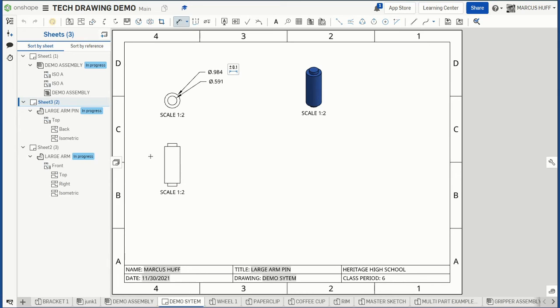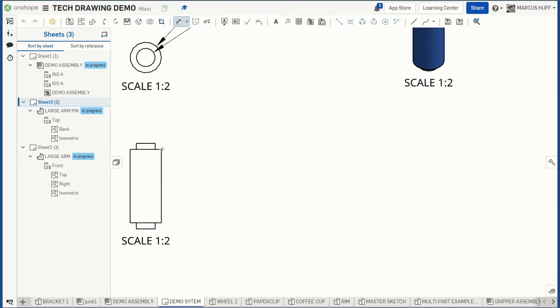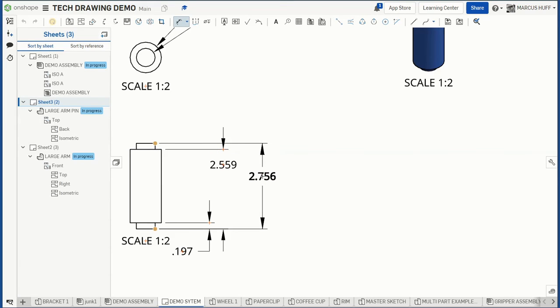Then for our drawings, if you want to do datum, feel free. Let me do a datum example. You pick one end and you work your way from one end to the other. So I'm going to go from here to here. This is my shortest measurement. And I'm going to click right there. And then I'm going to go from the same point here to the next one here, go to the right side of that. And then I'm going to go one more from here to here and go to this side. And I want that to be in the center.